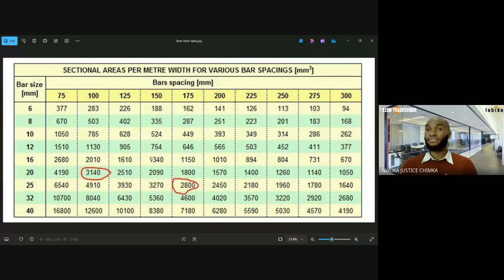So knowing that even you checking might get tired checking, it is best you go lower and say 150. Like if those people laying the reinforcement make a mistake, they might end up giving you 175, which is still within the area of steel. I don't know if you've gotten the scope. So in this case, I'll use 150 based on my principle, T16 at 150, all right?